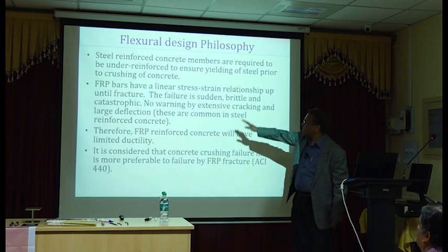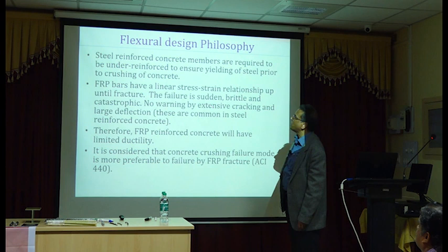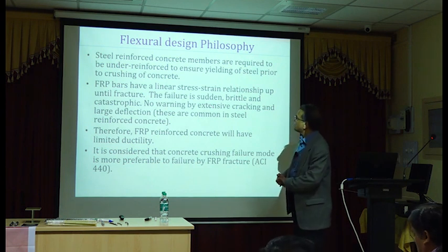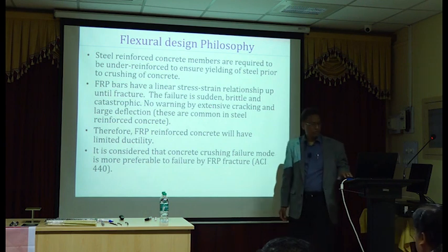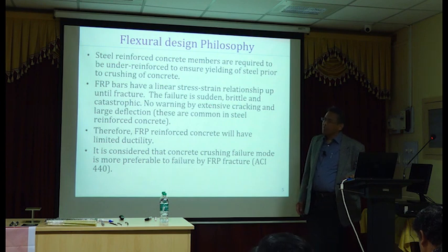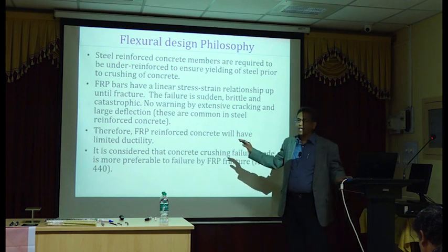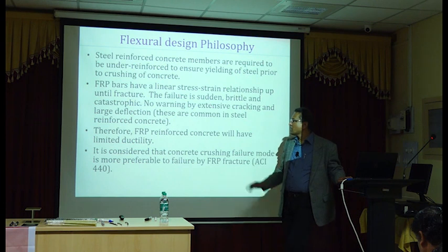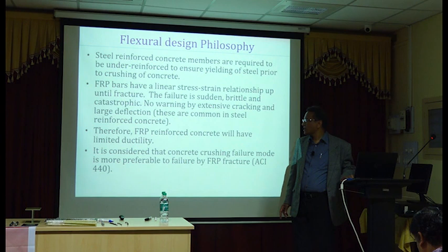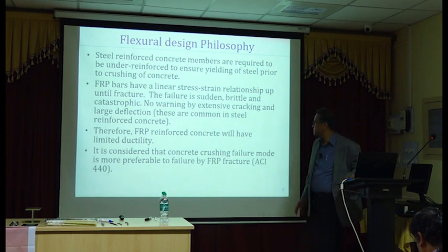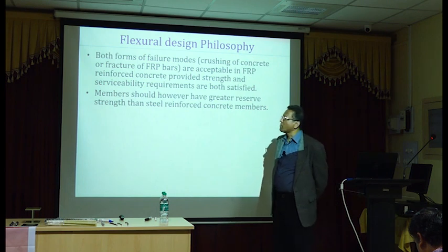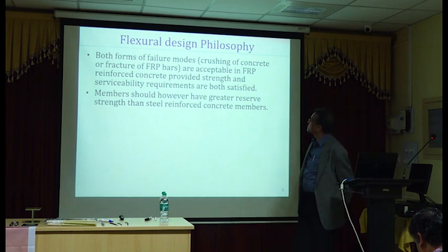So structural design philosophy, we already have this covered. So we prefer over-reinforced failure mode. And FRP reinforced concrete beams will have slightly smaller ductility, therefore you have to be using larger safety factors or smaller strength reduction factors. And over-reinforced section is more preferred than the under-reinforced section.